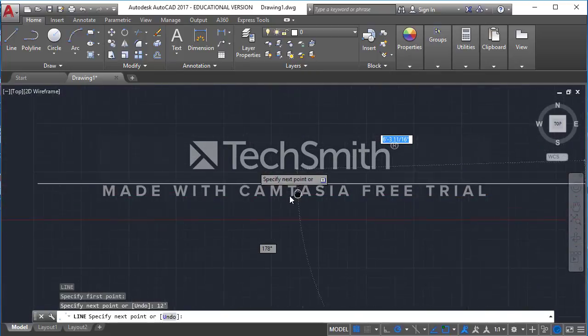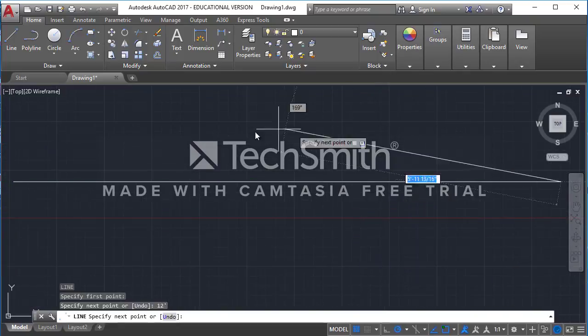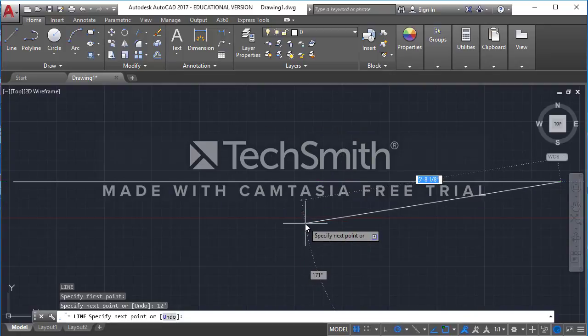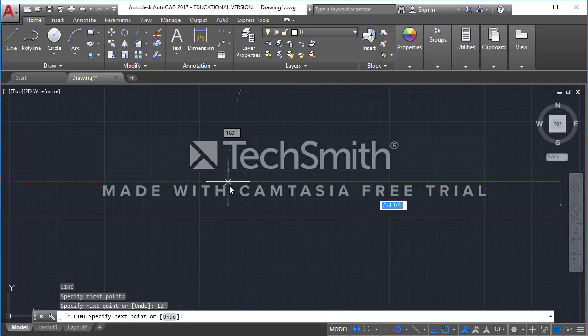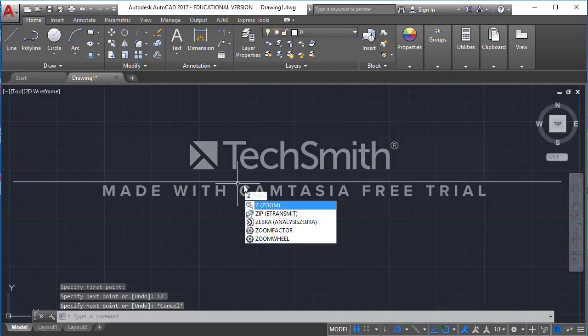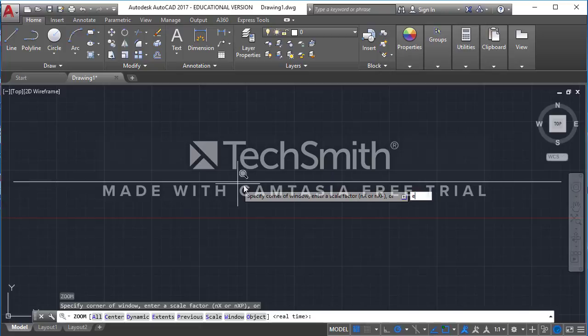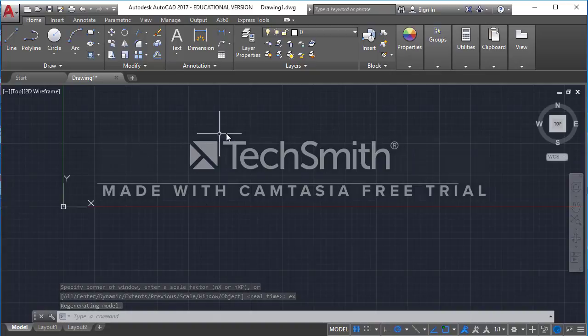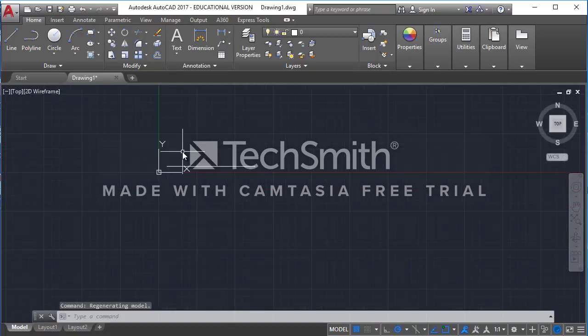I've also run into a little scenario here where I can't see all of my line. An easy command to zoom out and see everything clearly is the Z command. I'm going to hit escape first, but if I type in Z for zoom, I can hit enter, and I can type in EX for extents. What that does is it zooms whatever you have on your screen to fill the entire screen. It works pretty much the same way in the Adobe software as well. So that's going to be the zoom extents tool.